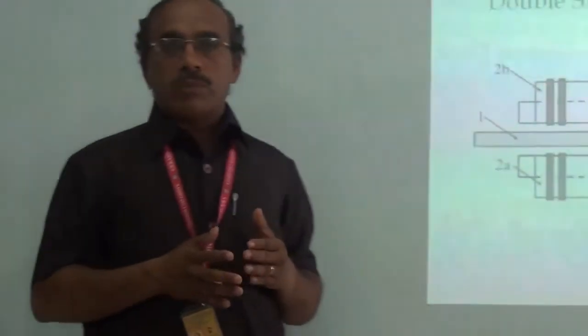Coming to the operation of the linear induction motor, when you supply a voltage to the primary, then by inducing current, the magnetic force will be developed on the primary, which is going to be induced on the secondary conductor. When the primary is stationary, the secondary conductor will move in the same direction as the magnetic force. In the other way around, if the secondary is fixed, then the primary is allowed to move, and the primary will move in the opposite direction of the magnetic force.